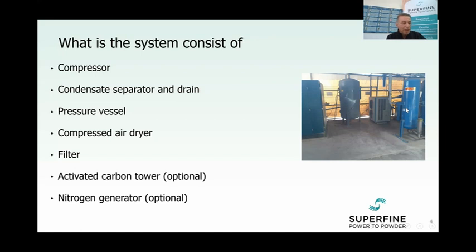There are also some additional components as options. It may be an activated carbon tower, or an oil-water separator, optional according to local regulation. Sometimes local environment laws and regulations state that condensate drained from a compressed air system cannot be returned to the sewage system due to the content of compressor lubricant oil. Water-oil separators are one of the most effective and economical solutions for this problem.